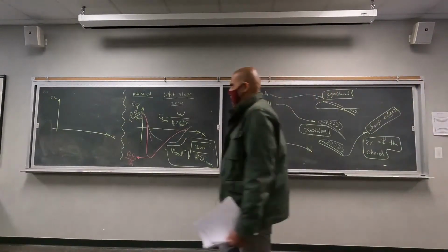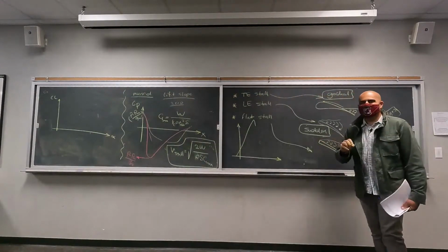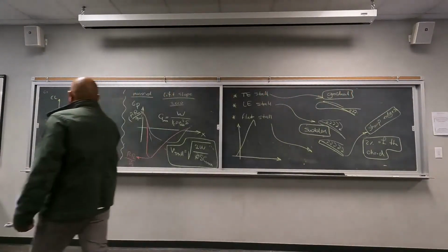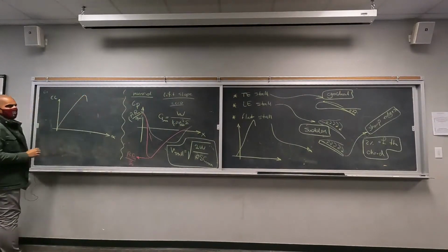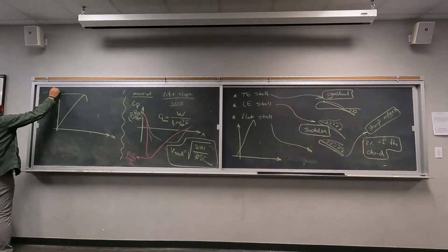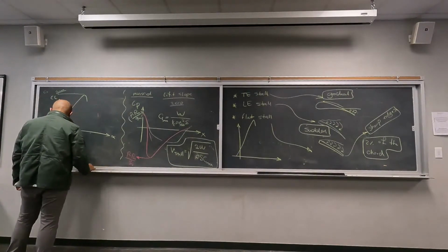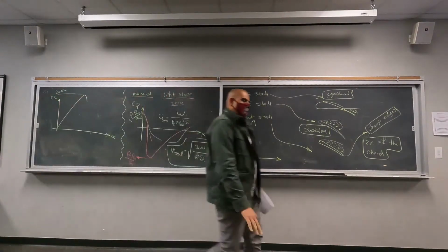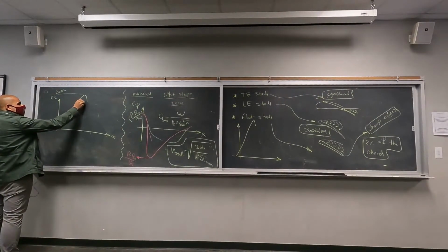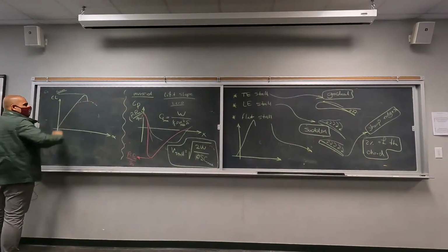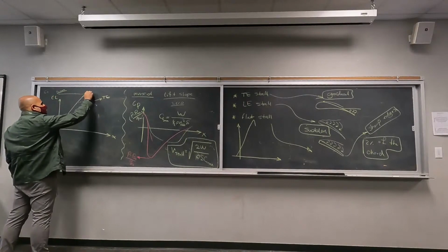The leading edge stall, yeah? Because the flow separation happens later, right? So the lift coefficient can go a little higher. So the leading edge stall usually looks like this. Very sharp decrease, okay? But the maximum value of the lift coefficient is very high. But for the trailing edge stall, there is a very gradual nature to it. So the stalling starts somewhere here, and it goes for a longer time. So trailing edge stall, I'm using the yellow color for this, and the leading edge stall. Okay.